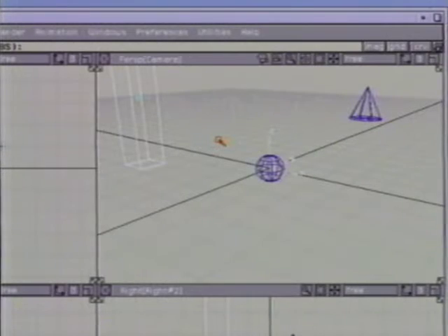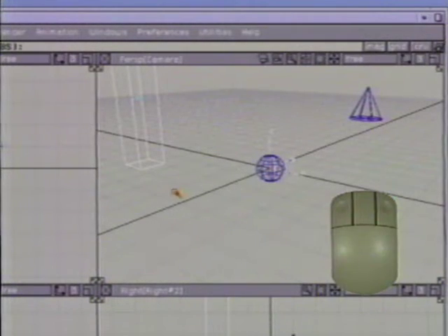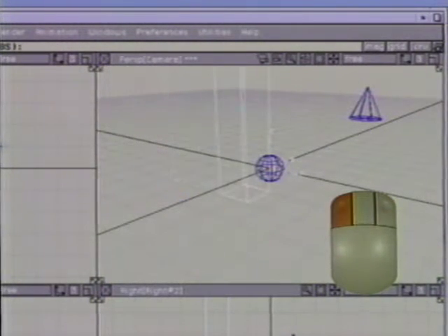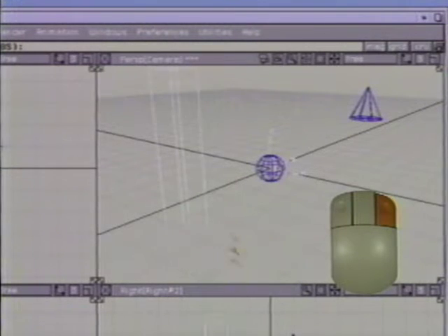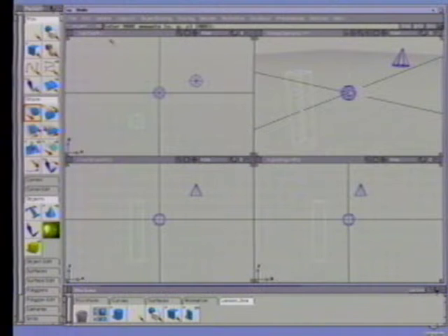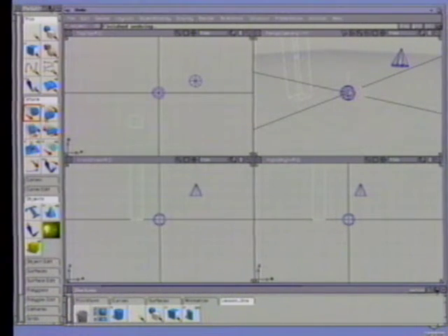The perspective window works differently. With the X-form move command still selected, go to the perspective window. In this window, click-drag with the left mouse button. The cube moves in the X direction. Click-drag with the middle mouse button to move in the Y direction. Next, use the right mouse button to move in the Z direction. If you don't like a transformation, select Undo from the Edit menu.